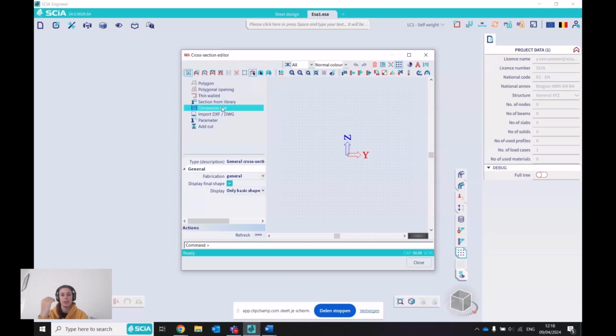parameters. If you import the section as a thin-walled representation, so with center lines, then it's also possible to calculate effective sections and buckling properties of the section. If you input it in a polygon kind of way, so the full surface is drawn and not just center lines with thicknesses, then you can still use the option called thin-walled representation, where you draw the center lines over your section, and then this drawing is used for the effective section design.